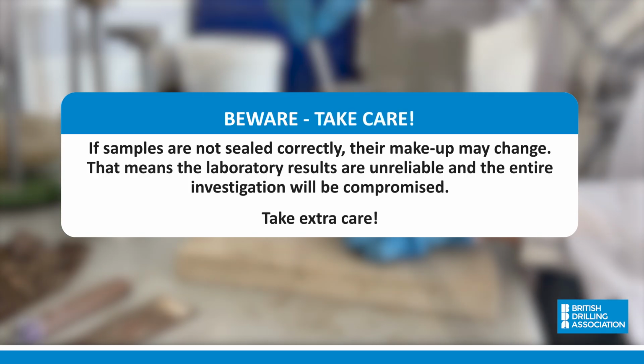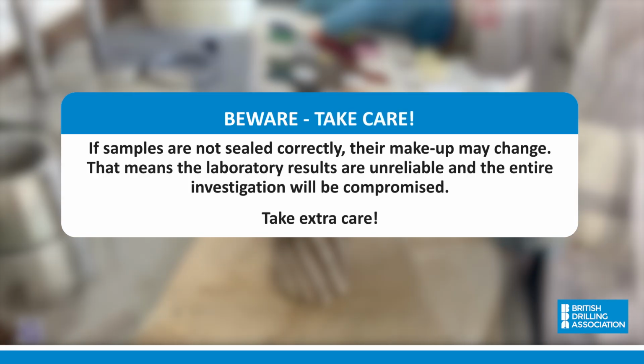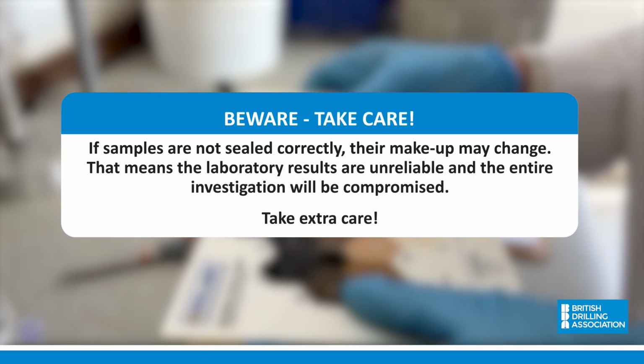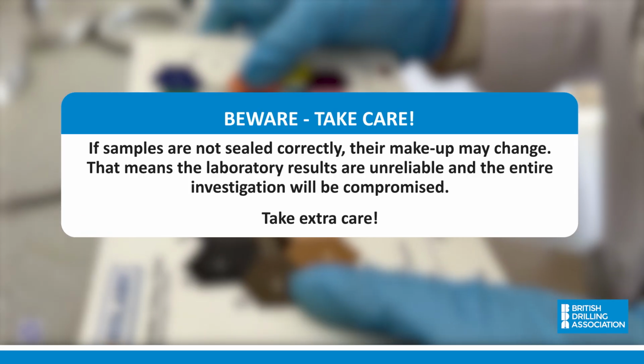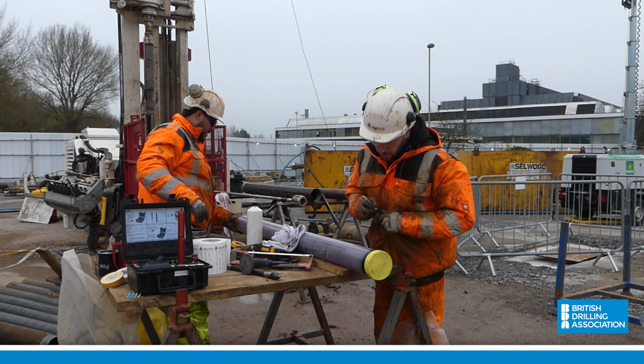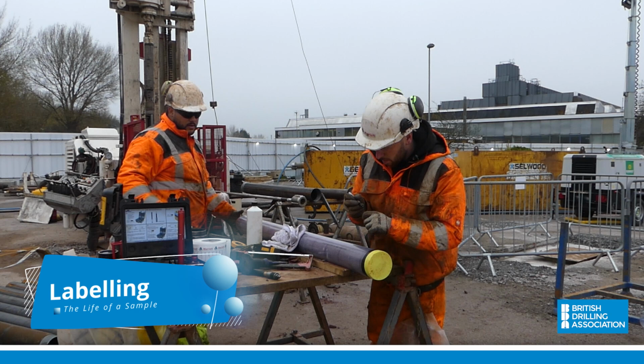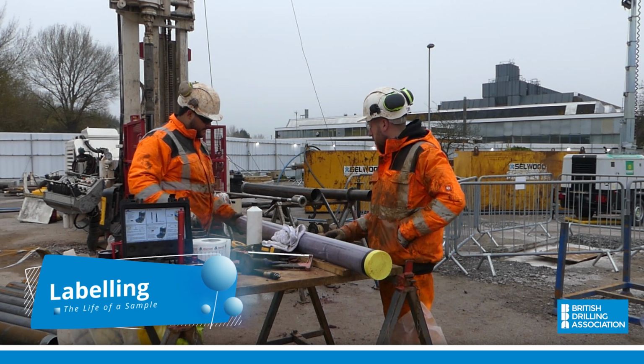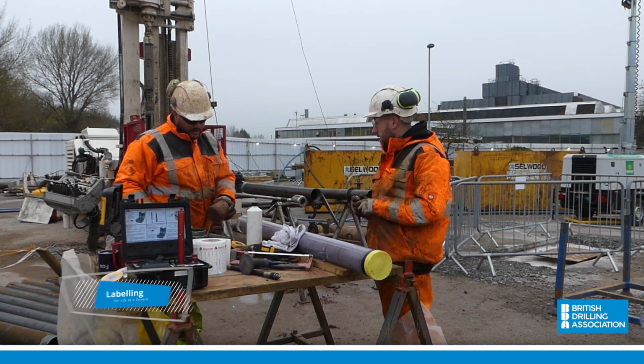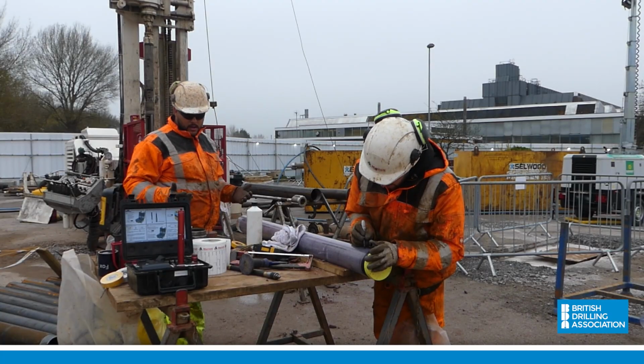So, if samples are taken but not preserved appropriately, they could deteriorate and become unusable. Once the sample has been retrieved and sealed, it must also be labelled correctly and the sample details must be recorded on the driller's log.